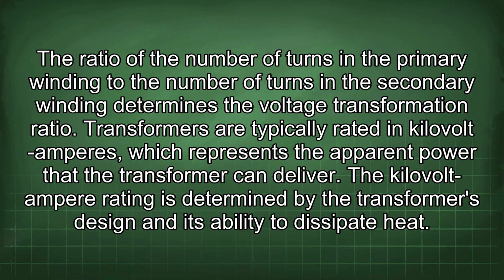Transformers are typically rated in kilovolt amperes, which represents the apparent power that the transformer can deliver. The kilovolt ampere rating is determined by the transformer's design and its ability to dissipate heat.